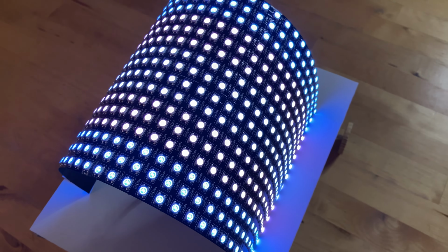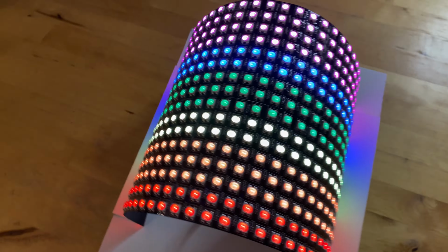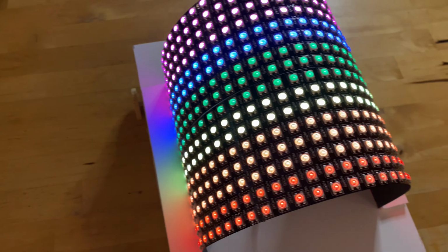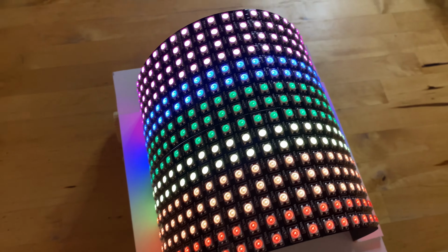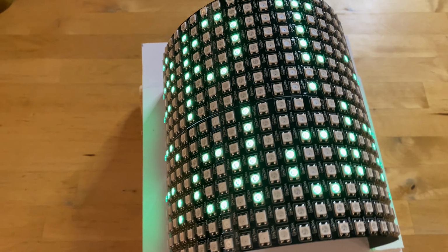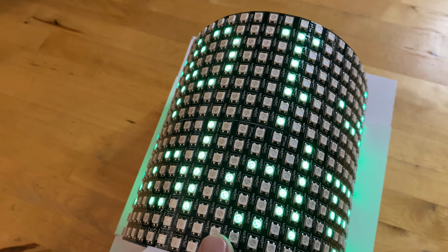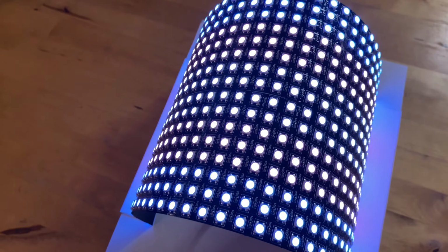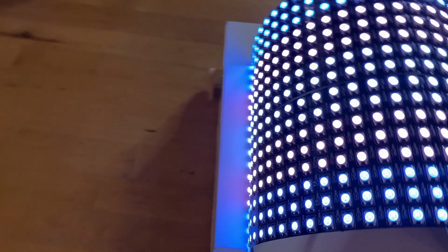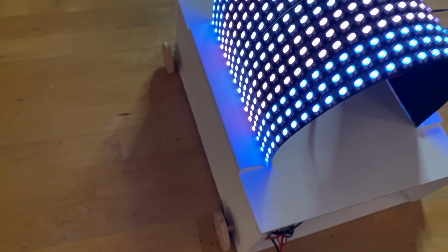So I started with a 10 amp power supply and did some experimenting, and then wrote in the code to switch it to not use all the pixels, or if I am using the pixels, not use all the brightness. And it's just 5 volts, and I switched it to just a normal cell phone power brick, and it's not getting too hot and seems to run fine. So I think this will be fine just with the power brick.